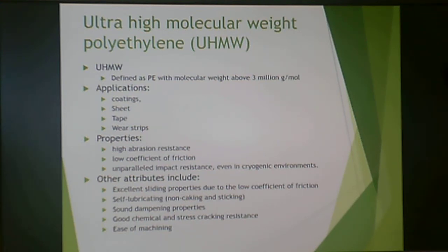And ultra-high molecular weight has superior impact resistance even in cryogenic or very low temperature environments. This has really good lubricity. In other words, it's slippery and it has a low coefficient of friction. It doesn't cake or stick. It has good sound dampening properties, and it has good chemical and stress cracking resistance. When it comes to polyethylenes, most of them have terrible environmental stress cracking resistance, so this is an improvement on that. Also, this is easy to machine.